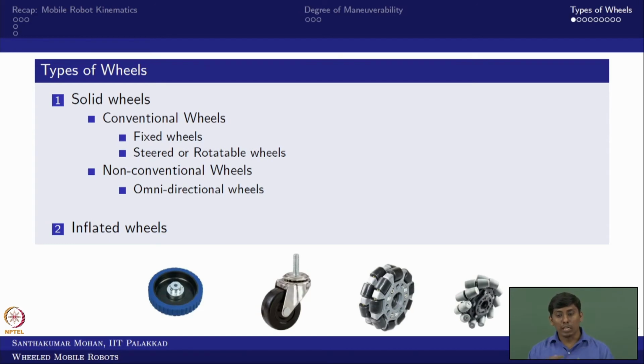What happens when you hit the ground, this passive roller also will take some energy. In that sense, if you imagine you have only Mecanum wheels, and all Mecanum wheels have only one directional inclination, then the vehicle will start moving in the lateral direction. So that is what we call Mecanum wheel. You know now the difference between Omni and Mecanum.